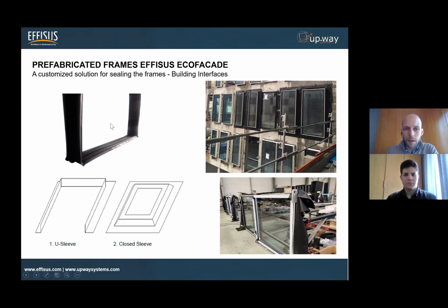And what's then a prefab frame? It's no more than having the full perimeter. So all this work that you normally need to do with plain membrane, and in each window, for instance, you'll find 4 corners to deal with, you'll just have the chance to get a prefab frame, so a complete frame that will just fit into your window, and you just need to seal all around the connection, the direct connection to the window.